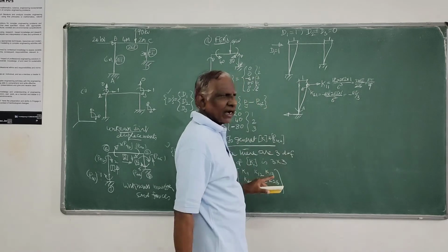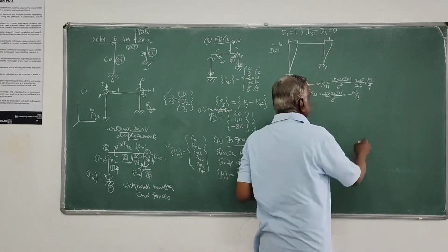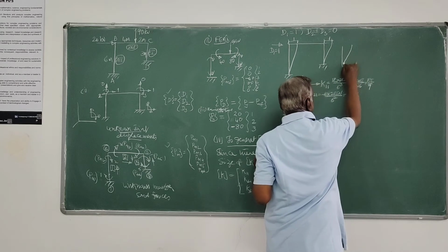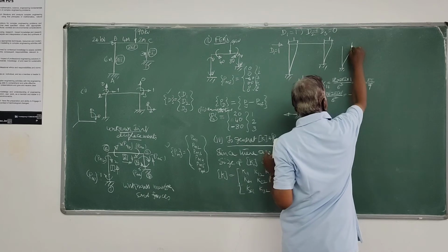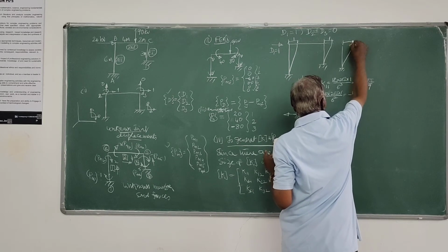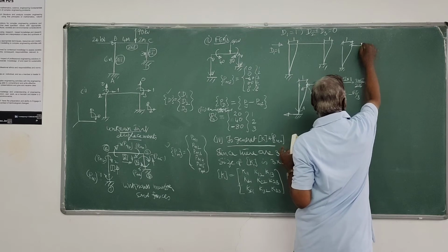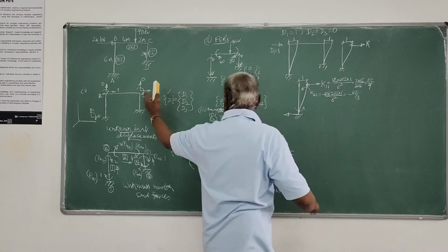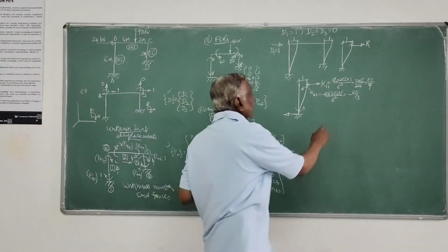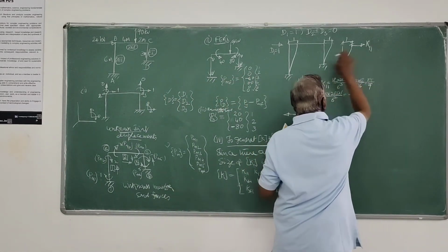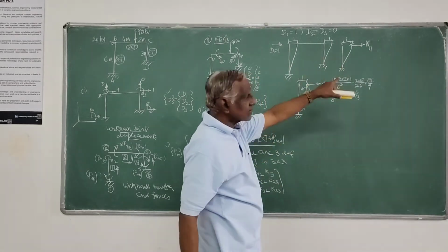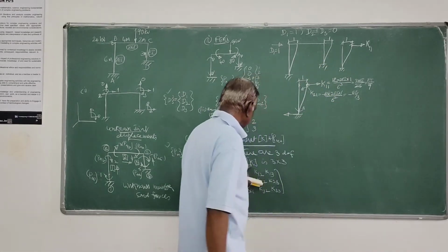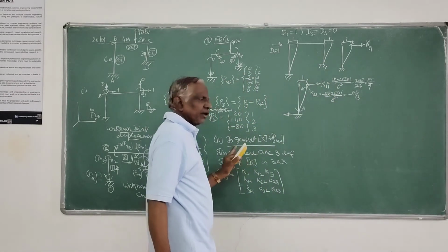So for this member, this member also undergoes displacement. So due to that, on similar lines, here there must be a force. This corresponds to 1 only, unit displacement is given as 1 only, so it is K11. Both are K11, and we have to add them together for finding the net value of this coefficient.